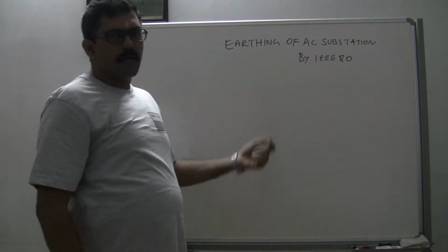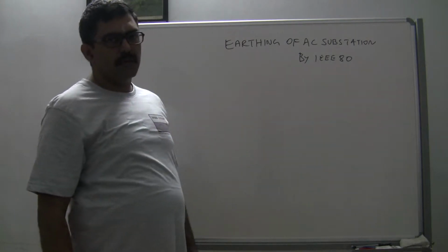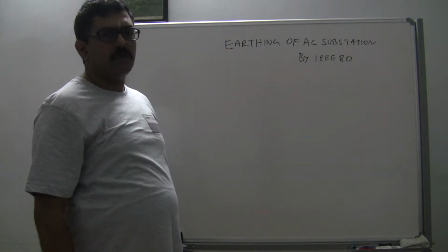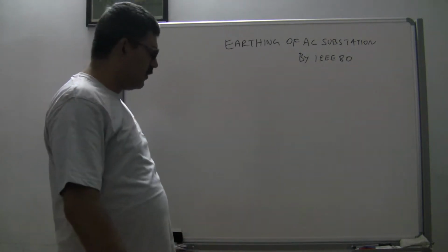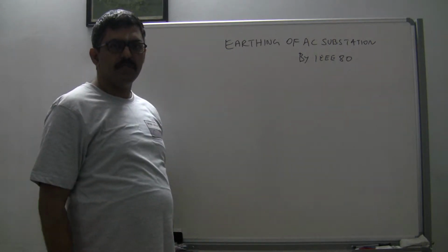We will be using the standard IEEE 80 to do the earthing of AC substation. So basically I will be guiding on how to design the earth mat of an AC substation.